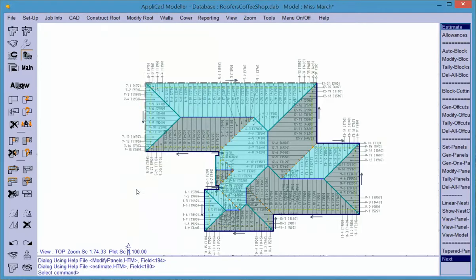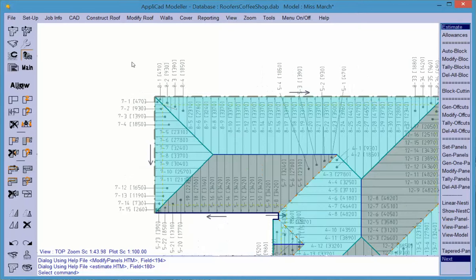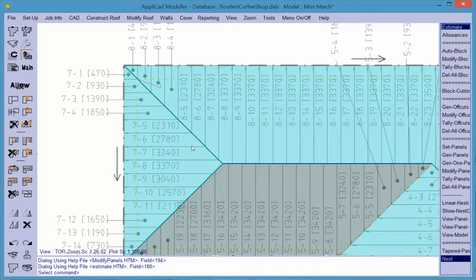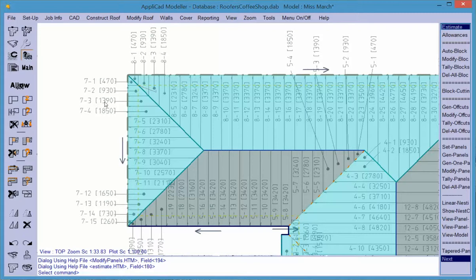So that's generate panels. The key difference between this process and blocking, for example, is that there is no attempt to reuse the off-cut material in this instance. By the time the sheet is hemmed at the bottom and turned up at the top, the off-cut is generally a bit bent and broken, so it's not really practical to reuse. But in any case, with a narrow panel, the off-cut is not a huge percentage of the roof anyway. So this is typically the way roofs are done in North America and in parts of Europe, and quite a bit different for those of us down south.